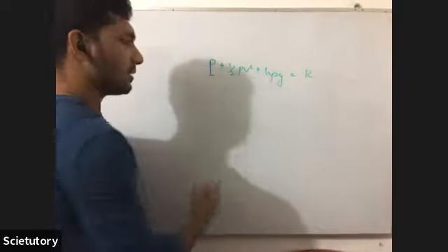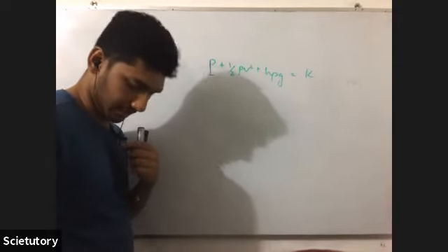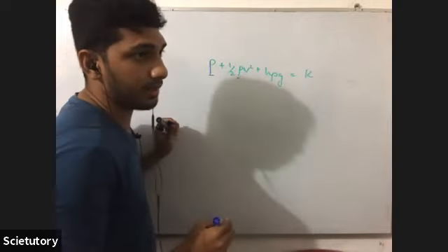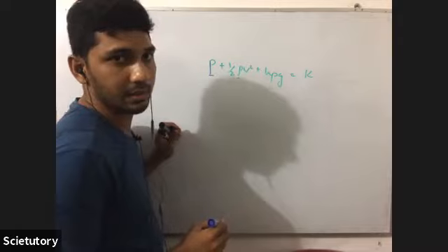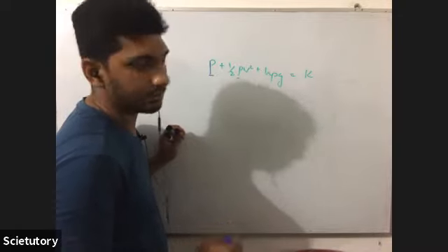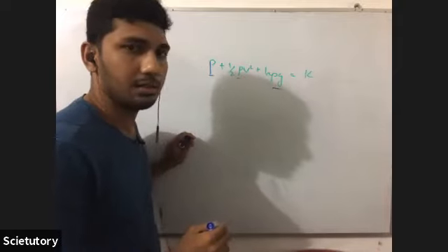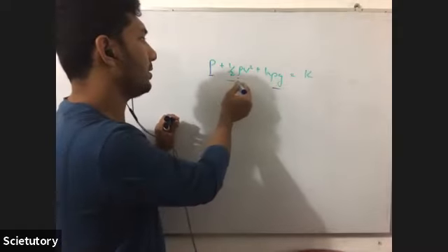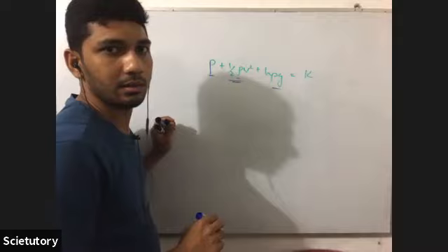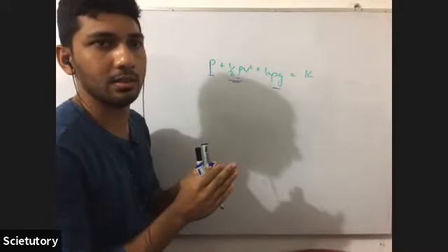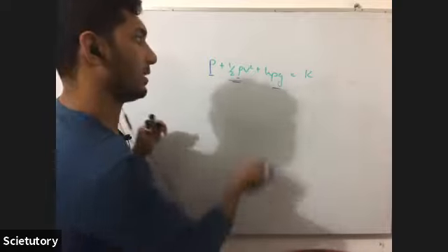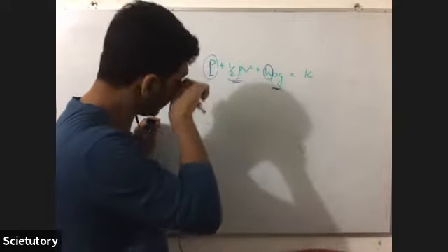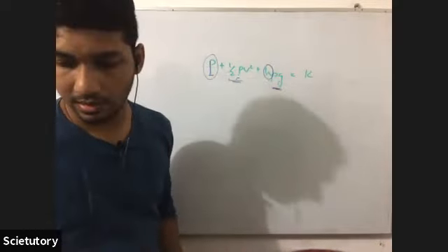Now the P is actually called static pressure. Half of V squared is kinetic energy per unit volume. This is potential energy per unit volume. So this is determined by the velocity, or the cross-sectional area. The velocity is affected by the area of cross-section. This is determined by the height. This is determined by these two. That's how you explain this equation.